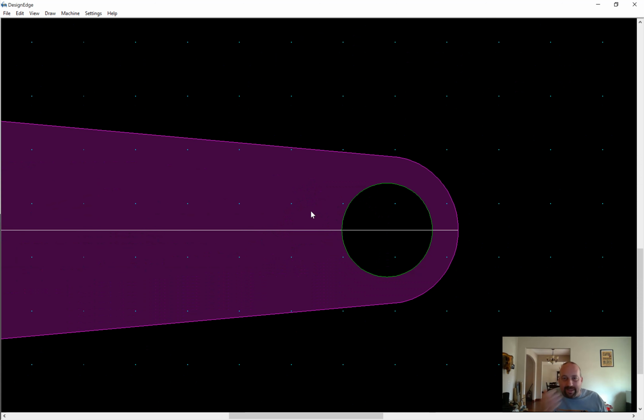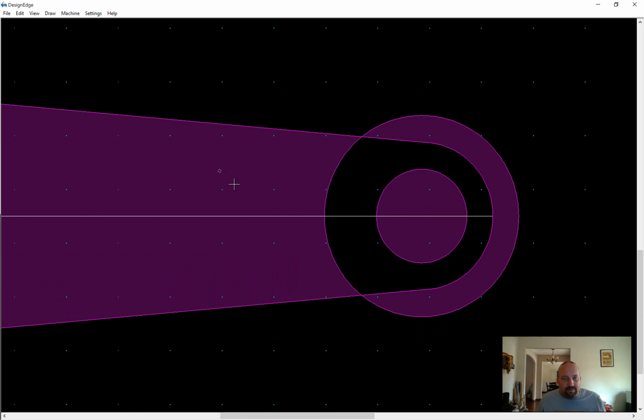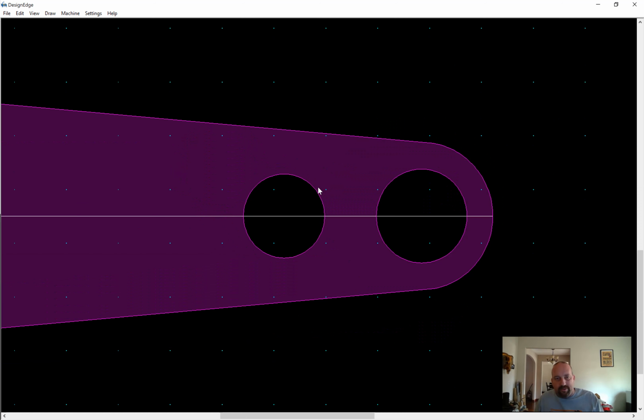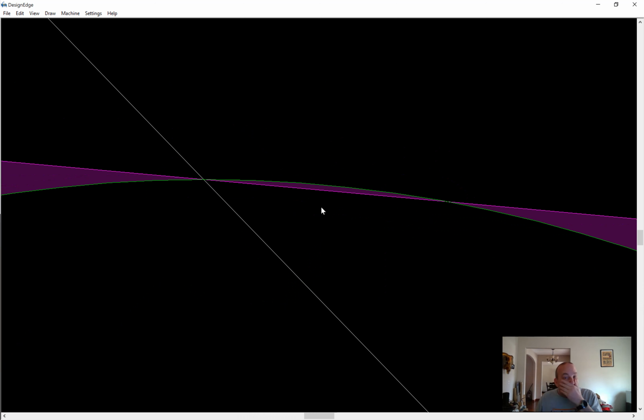I don't remember if that's how that was done or not, but O offset 1 inch as we were told, hold control, and then we were making a Q and moving it from this quadrant to that quadrant, and then we got rid of that, and then we drew a line from that intersection orthogonal up like that, and then I think he scaled this circle from that endpoint or quadrant and that intersection up to that intersection.